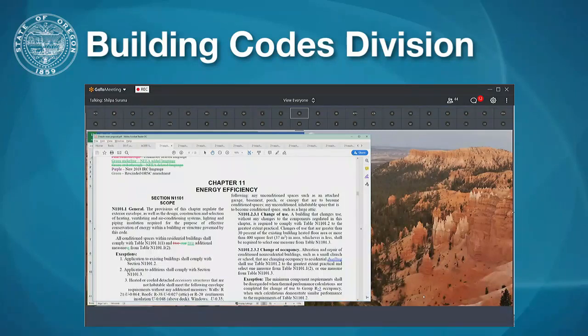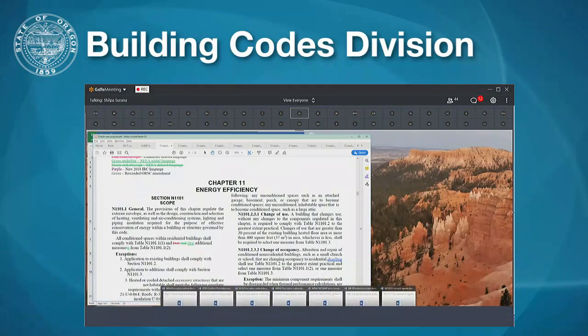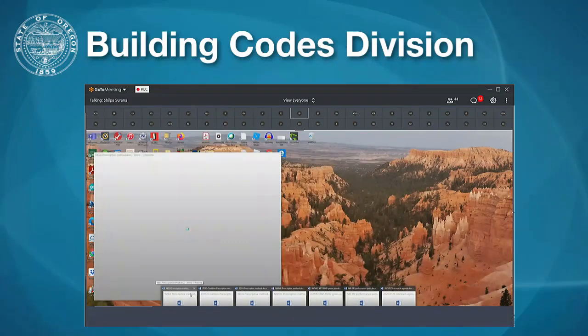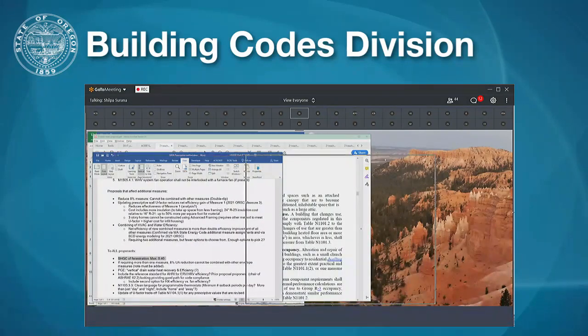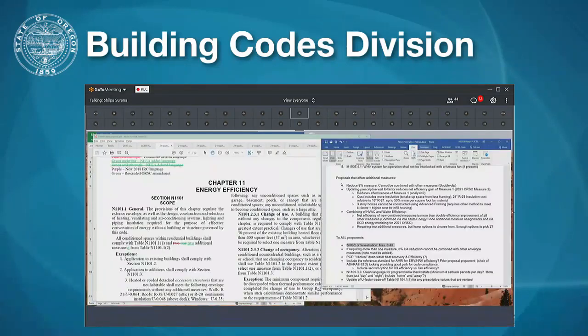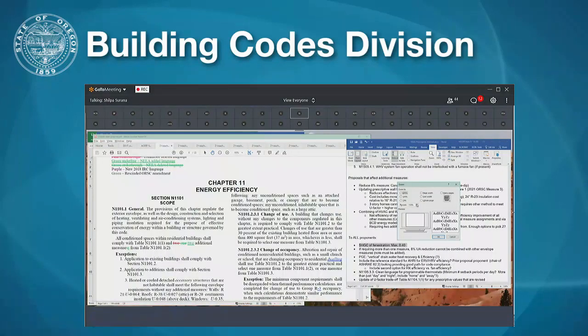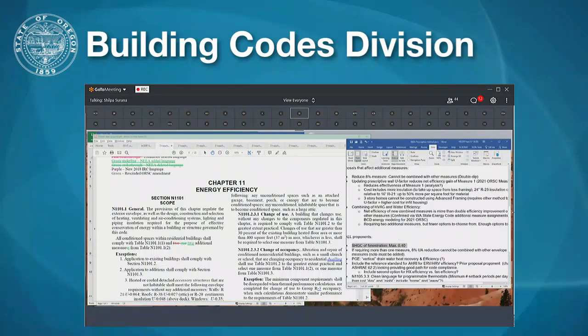As I'm going through the prescriptive requirements, I would also recognize that we proposed an advanced framing wall option using R23 and 24 inches on center framing. We could not run our analysis to include the energy savings from this update, but we did factor in the cost savings using this strategy.